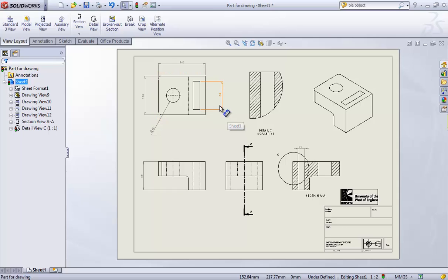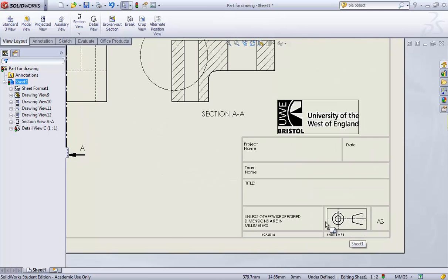So yep, this is how you create drawings in SolidWorks 2020. At least it's not going to change for any of the future versions, I suppose. Main steps, just to summarize, is selecting a correct sheet size. For this coursework, you are working on A3. The sheet type is ISO. After that, we edited this particular sheet to the correct format, so we added all of these details in.